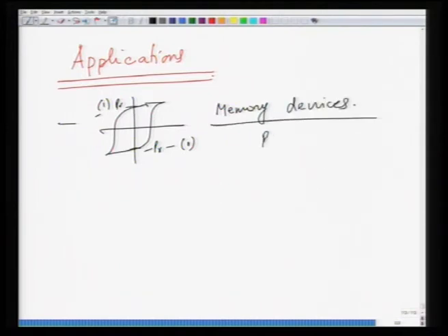Materials like PZT, which is lead zirconate titanate, bismuth Bi4 minus X LnX Ti3O12, which is lanthanide doped bismuth titanate, strontium barium tantalate, strontium bismuth tantalate. All these have been tried for memory devices, and they have been successful to some extent. The advantage of these materials is they have very high radiation resistance as well. So, they can be used in space without damaging the polarization.